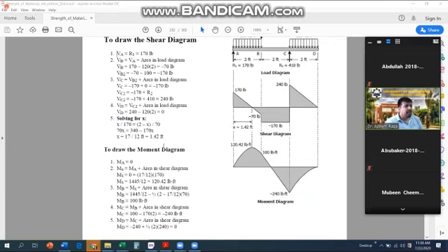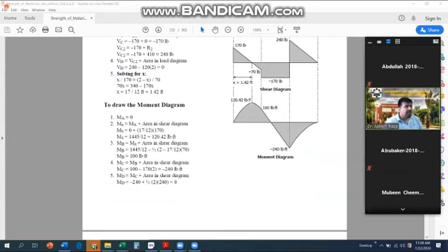And we will compute our bending moment. So we need to find the moment at point, let's call this point x, just like here. So change in area: 0 plus 1 over 2 multiplied by 170 multiplied by 1.42. The answer will be 120.42. So you draw 1 point here.